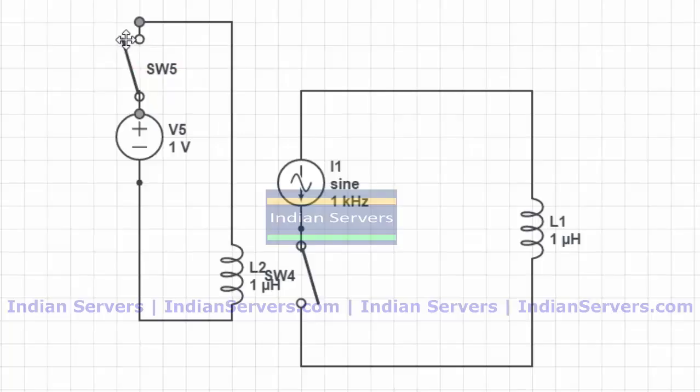So whenever this switch is closed, this particular voltage, it may be 5 volts or 12 volts, will be given to this coil, and this coil will act as a magnet, a temporary magnet. At this time, this switch will close automatically because this is an iron particle which tries to attach with the magnet.